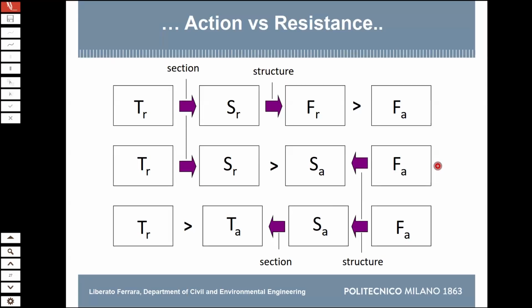And it can be different if you apply the safety factor before or after, because you calculate the compressed part and so on, and that will affect it. Material first, the results are different, for resistance moment capacity or resistance shear.